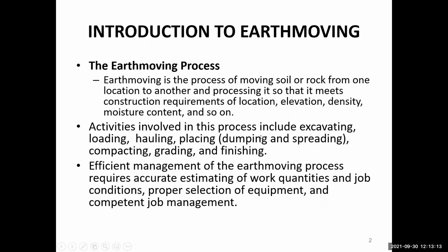So what do we have in this topic? First of all, introduction to earth moving. So what are these earth moving operations? In every civil engineering project, earth moving operations play a very pivotal role, because you all know that civil engineering structures are constructed on the ground, and the ground surface is not as desired as we want. So we want to prepare the ground surface to the desired level and characteristics. So the earth moving process is the process of moving soil or rock from one location to another and processing it so that it meets construction requirements of location, elevation, density, moisture content, and so on.